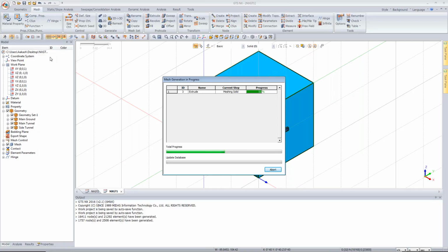So even if you want to do the manual activation and deactivation, you should make sure that whatever you are deactivating is the correct named mesh set, because if it's not properly named, the issue will come with the construction stage definition.